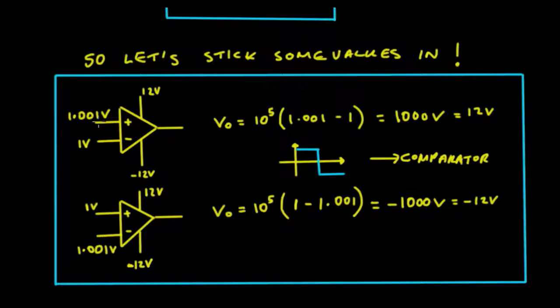So you can see here why they get the names inverting and non-inverting, because the V plus side is the non-inverting, so we can see that there's a difference in a voltage here, and so the voltage difference there goes up, the output voltage goes up. In this case here, when I connect it around the other way, as the voltage difference goes up, the output voltage here goes down. Okay, so it inverts it. So that's how you get the term inverting and non-inverting. Okay, so just as a reminder, the V plus side is the non-inverting side, and the V minus side is the inverting side. Okay, so let's have a wee look inside the Opamp.